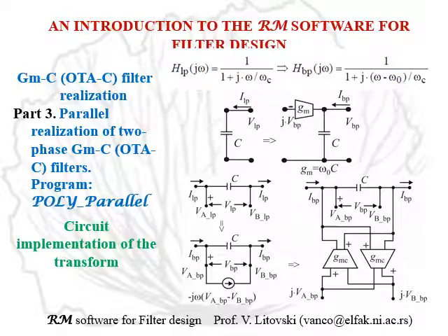So the top line is I, the bottom is Q, because it is shifted by j. And this is a connection between the capacitors in the two chains or two filters which are processing the I and Q. And in that way, we are getting a two-phase filter.